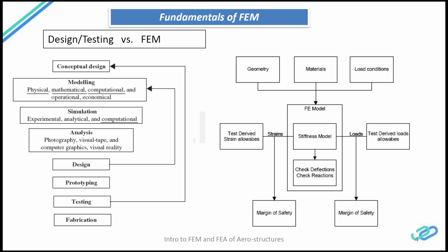Once the testing is satisfactory and passed, and there is no failure of the component and no visible damage, or if it sustains the damage for 3 seconds. Usually in aerospace structures they have a fail-safe structure and safe-fail structure. The high-level FAA, Federal Aviation Regulations, requirement is that the structure should withstand the ultimate loading for at least 3 seconds without any permanent damage or permanent deflection.